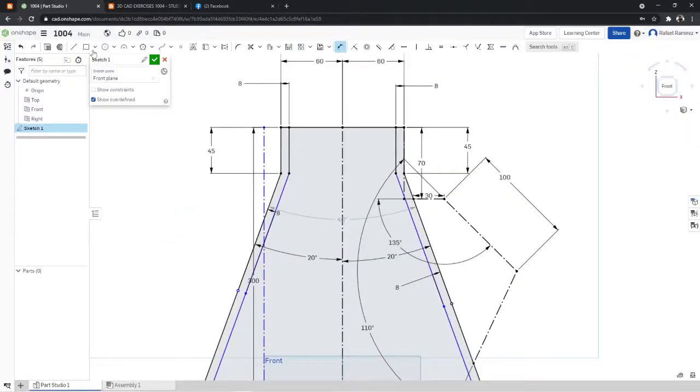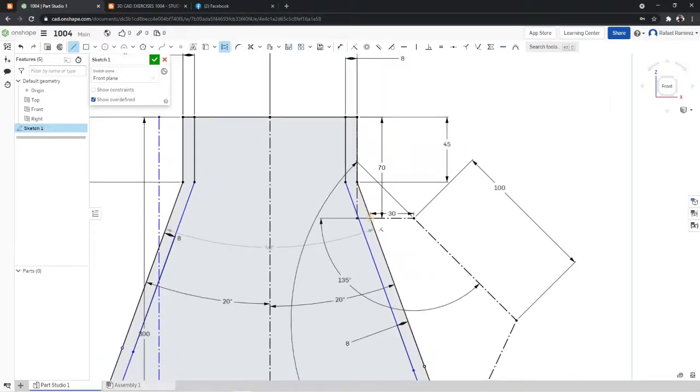In order to do so, the same thing as what we did earlier: click on this one, click on the construction line, and since this is at the middle, dividing the 10 millimeters by 2 will give 5 millimeters here. So 5. The same thing downward, I'm gonna put 5. So 5 plus 5 would have a 10 millimeter thickness across. The same thing here needs to be 5. I mean, not that one. Yeah, that needs to be 5.